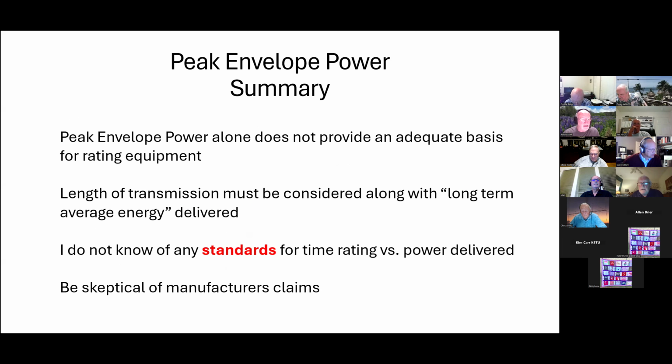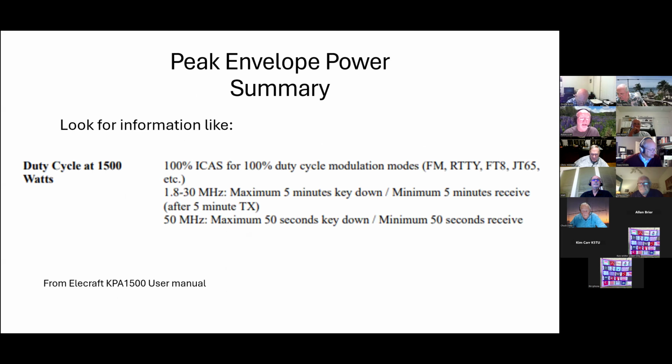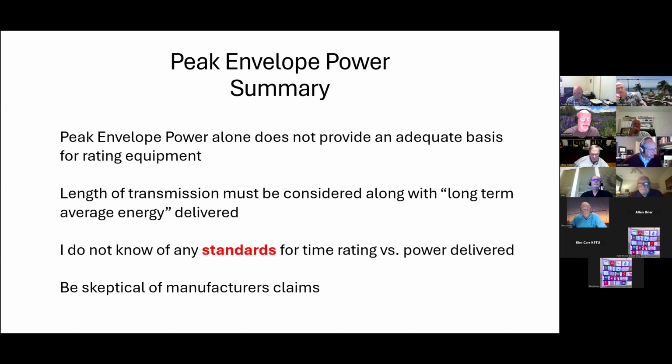Now, when I talked about not being able to find data, I'm talking about being able to find data on the duty cycle. There is no standard for a duty cycle that I could find, in the rules or just in everyday usage, or in the FCC, in either place. I looked at several people who've calculated it, and the FT8 duty cycle is a good example. It's not 15 seconds, it's 12 and a half seconds, followed by 1.5 seconds for decode time and 15 seconds till it starts to transmit again.